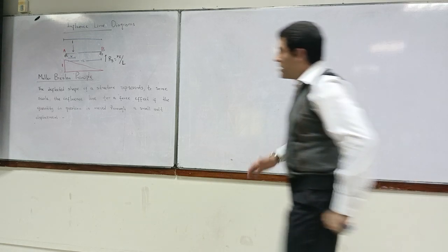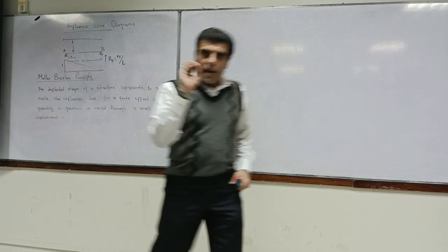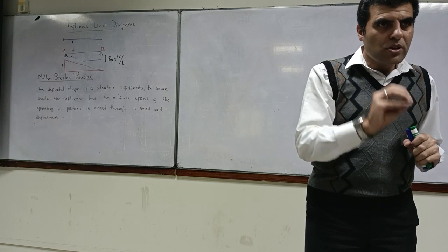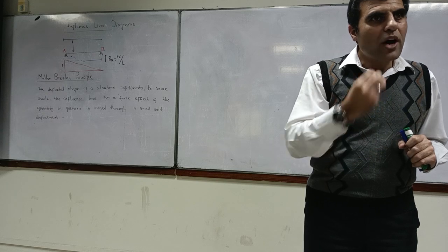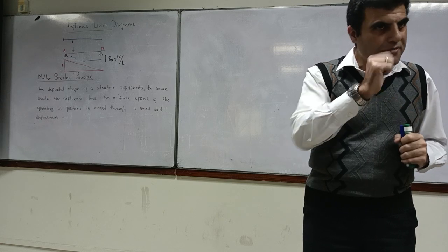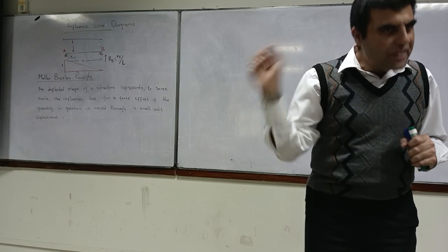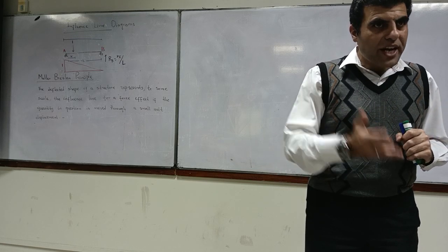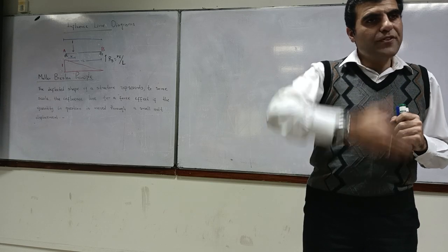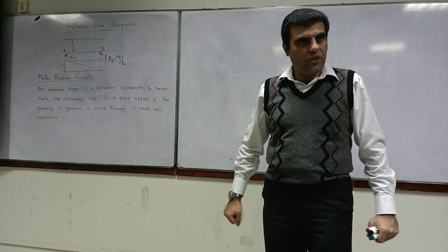Okay, you are asking whether the load won't have any effect? No. This principle is just saying, forget about the load. First of all, understand what you are after. The first step is, I am after reaction. The second step is, what restraint is applied at that point. Remove that restraint, and then apply unit displacement in that particular direction. If you apply unit displacement, you will get a deformed profile. That deformed profile is your influence line diagram.